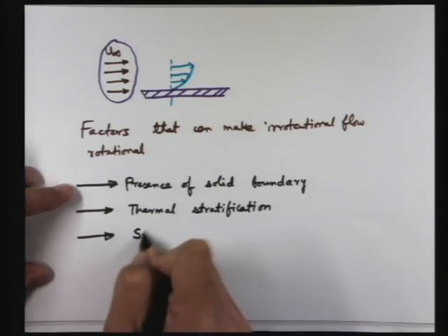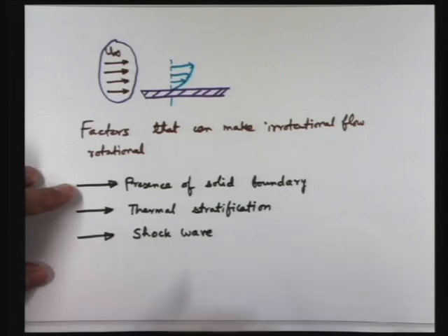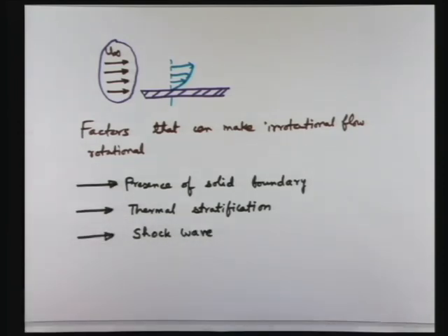Shock wave. At least all of you have heard the terminology of a shock wave in a compressible flow. So you have abrupt discontinuities in the properties of the fluid as you confront a shock, and then a shock wave can convert an irrotational flow to a rotational one. And